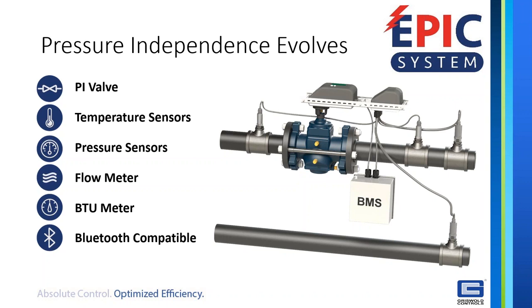And so pressure independent valves evolved into a temperature independent system. If you're looking at our EPIC system, the PI in EPIC is red because it is a pressure independent valve based system. We take our Pinnacle in the smaller sizes and our MVP valve in the larger sizes, and we build around that a system to directly control the delta T across some heat transfer equipment. But the heart of it is still the pressure independent valve.